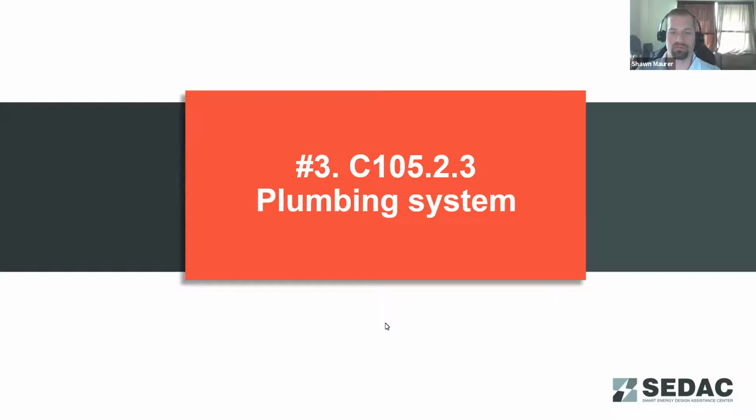Looks like we've got most of our poll answers in, so we'll share those results. First question, if full Z channels break the continuous insulation, most people picked up on that yes, that full Z channels do not allow insulation to be considered continuous insulation.